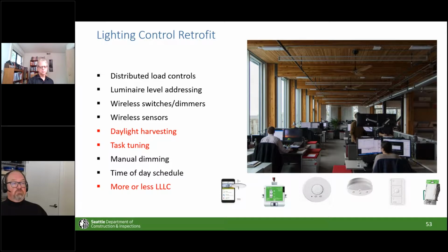We used a parts and pieces approach with a standard, actually a budget, network lighting control system. Nothing special about this system. I use eight or nine of them in my network lighting controls classes that could all do the exact same thing. We added in load controllers to make each individual light fixture dimmable. We added in occupancy sensors that overlapped control zones. We added daylight sensors, everything. We did all these things.